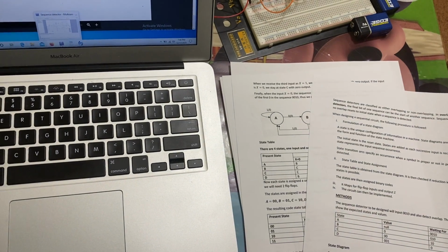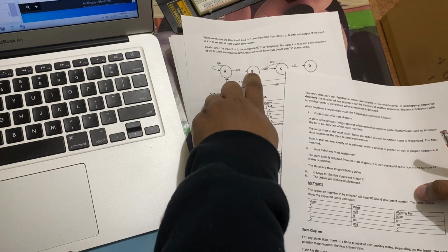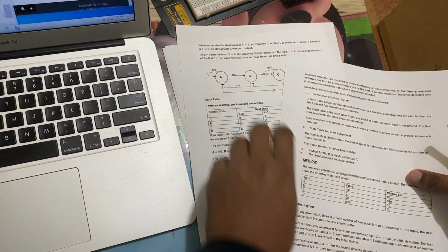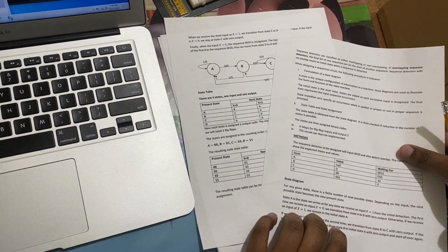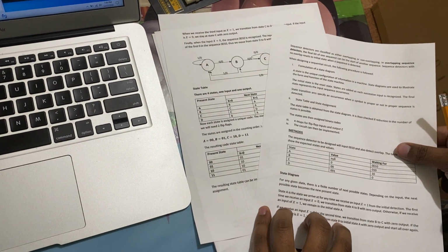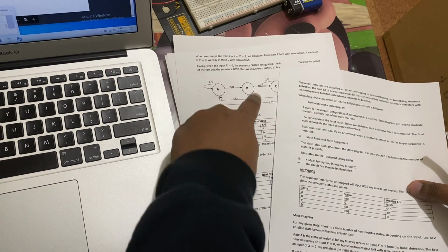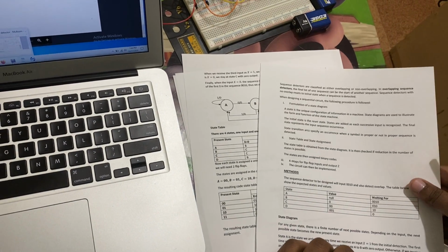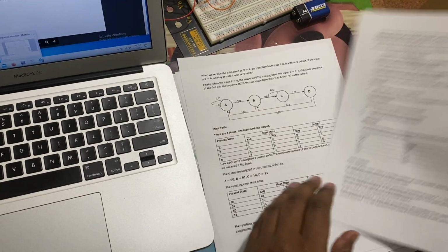If we receive an input X at state B for the second time, the transition moves from B. If we have an input of 0, it goes to state C with 0 output. If the second input X is 1, from here it's going to go back to state A. That's why it says here in my writing, with 0 output, and it starts all over again.